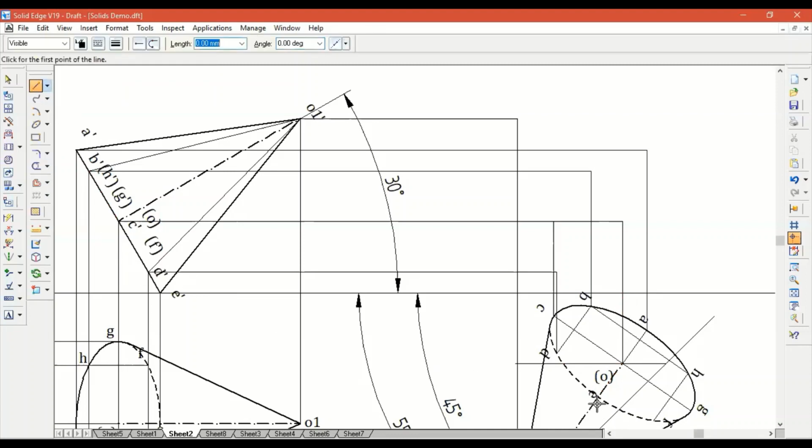Then I'm going to go to E. Remember, E is the point on which the axis is resting, or rather the solid is resting. So it's going to be the X1 line. Then F. F lies along D. So right there. And then G. G is in the middle along C and O, which is there. Then H close to G, but up here.